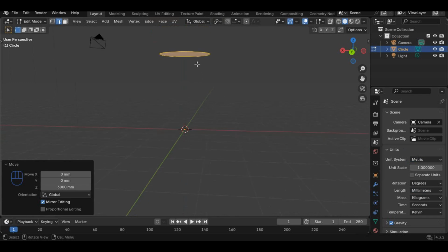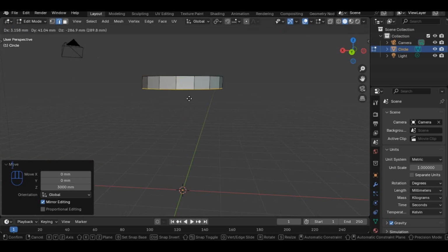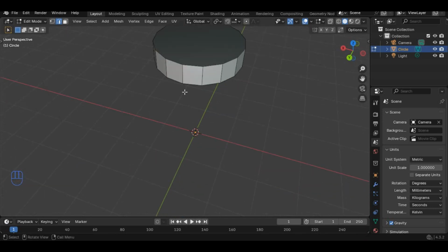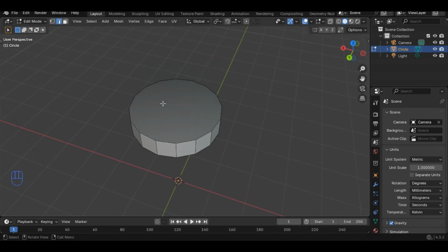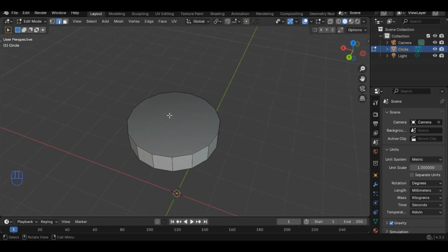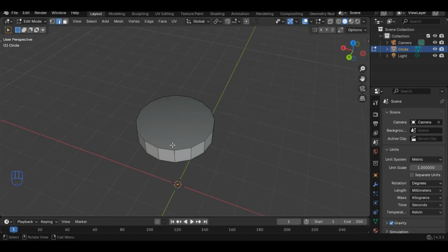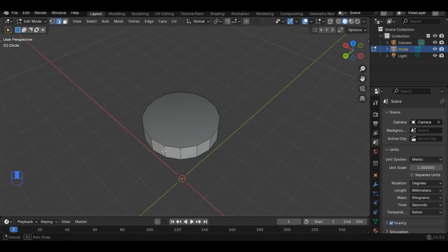So now I want this to actually be extruded, so I can give it an extrusion of, let's say on the z-axis, minus 50. What I want to do now is create the recess on top of this place where, if you're going to be using a screwdriver, it's going to fit in. I could design the edges of my recess to be straight up rectangular, or design it to be fitted for a star screw.